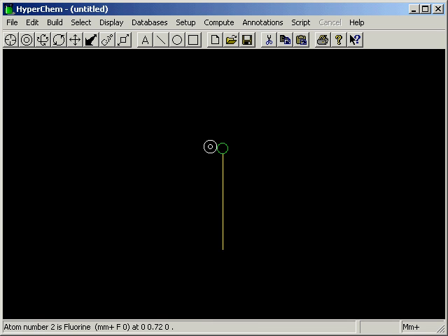So what we're going to do is assign velocities, a velocity here in this direction along the positive x-axis and a velocity for this atom along the negative x-axis, and that will cause the molecule to rotate around the z-axis. When we assign velocities, we can either assign velocities all at once to a set of atoms, either to a selected set or to the whole set. If we don't have anything selected, then the velocities will be applied to every atom.